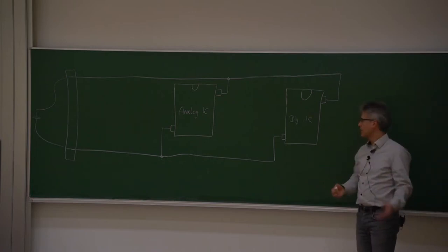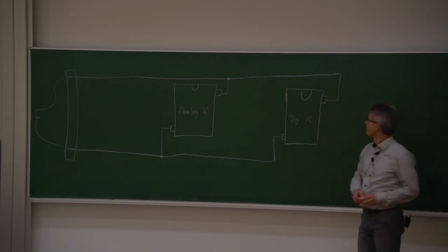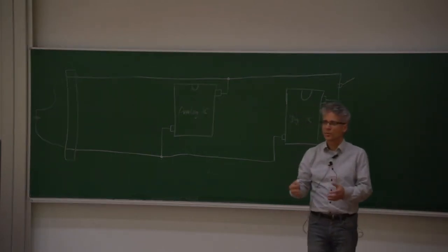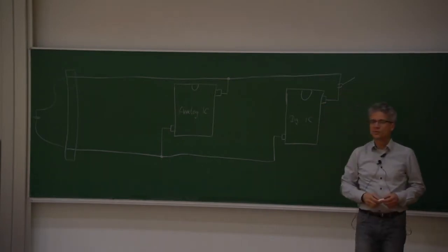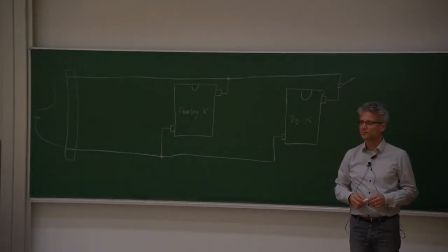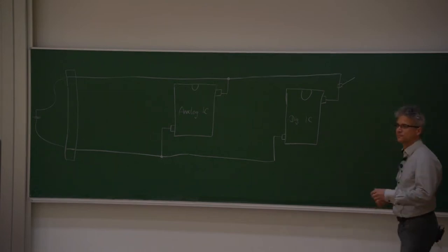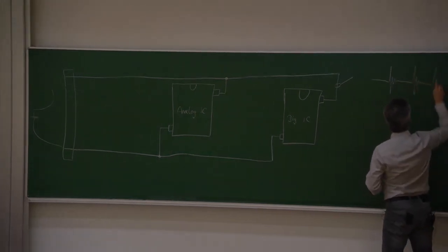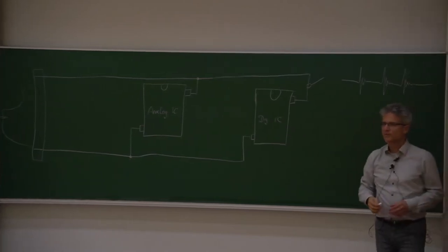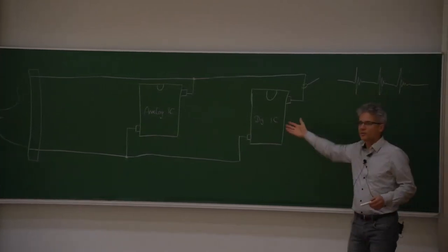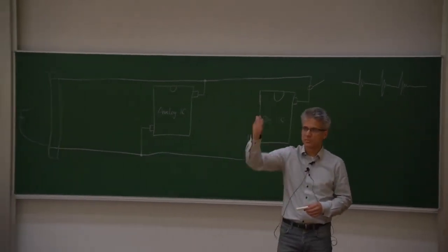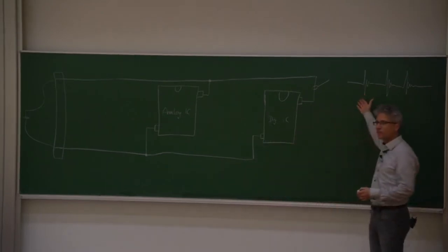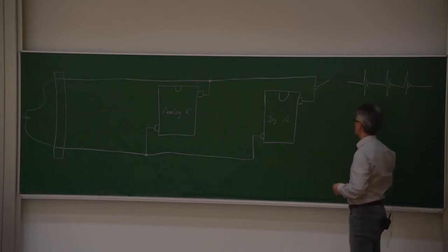They are all switching at the same time at a certain frequency, 16 megahertz. So if we are placing a current probe on an oscilloscope and monitoring the current, any idea how the current would look like? We have a lot of spikes in the probe. Most probably the current would look like this. At the repetition rate of 16 megahertz, we have these big current spikes. Current spikes are coming from crowbar current, dynamic switching current, and all the combinations of that.